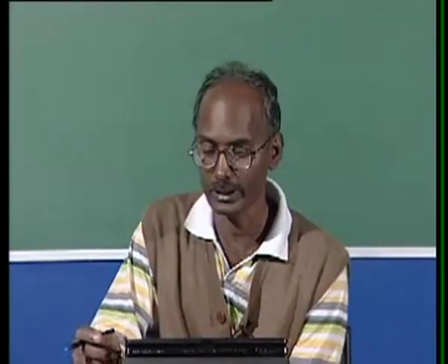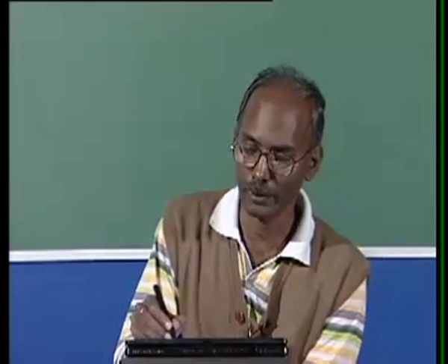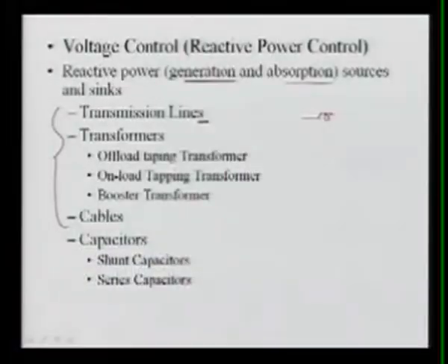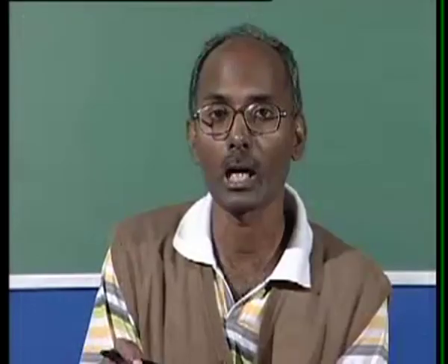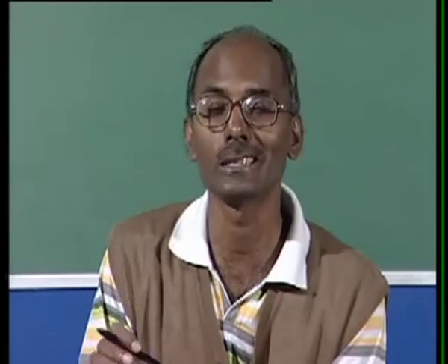Why am I saying this? Because if we model a transmission line, this is your transmission line reactance, then it will have some resistance, and let's suppose I am modeling it as a pi equivalent. So what will be here? This will be the charging capacitance. Let's suppose a pi model. This is grounded and this is between bus I and J. Now whether this whole element is generating or absorbing depends on how much it is consuming and how much it is generating.